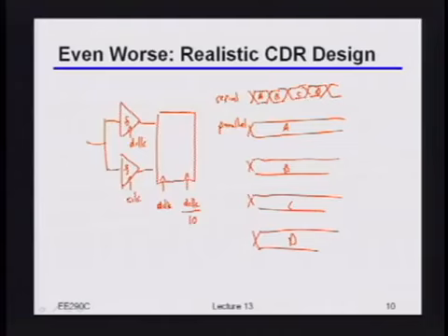So typically then what will happen is you'll take all of those parallel things, and rather than just doing all the same computations you would have before, you'll just look for some aggregate behavior. So you might say, okay, let's say I do a divide by 10. I may have had 10 possible up and down signals, right? So I say, okay, only if I get more ups than I do downs across that whole window, only then will I actually move up, right? Or maybe only if I got 2 more ups than I got downs, only then will I move up, right? And so on and so forth.